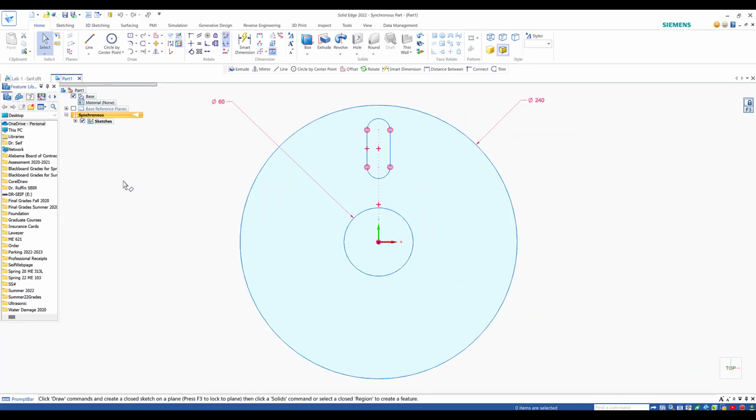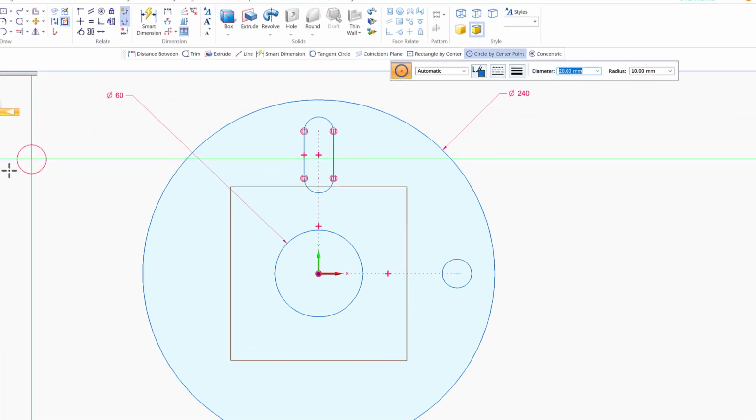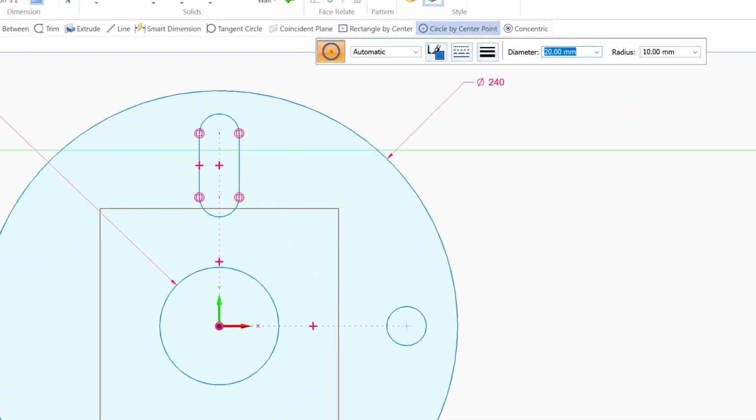Some people sometimes draw a line as guidance. If you feel more comfortable doing that, that's fine. Let me show you something. I can do the method like this. I need the 20 for the first circle. I know that it is on the horizontal if I see the dashed red line. When I see the dash, that means it is on the line. I click, and it is done. Suppose I don't want it. I'm going to draw a line, which is another way of doing it. So I'm going to go back to undo.